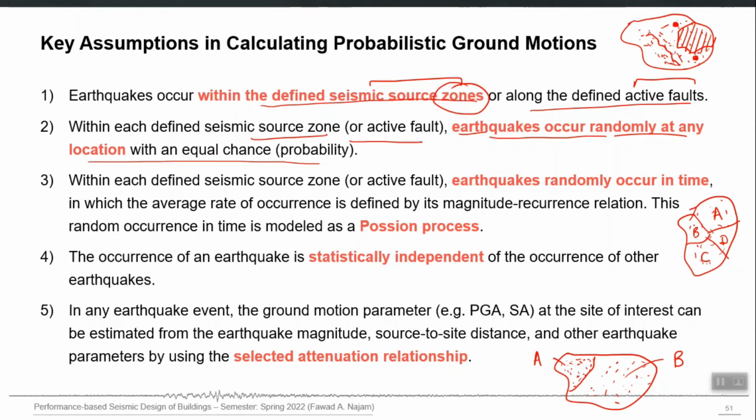This is one of the major challenges actually, because it may affect our future forecast results, the hazard results. But once we make a source, for example, source A is delineated and we declare it as one area source, then within that source we cannot say that in this particular region earthquakes occur more and in this region earthquakes occur less.